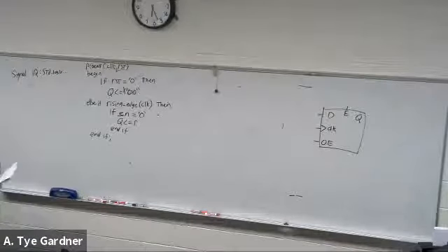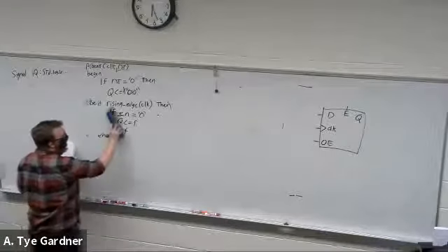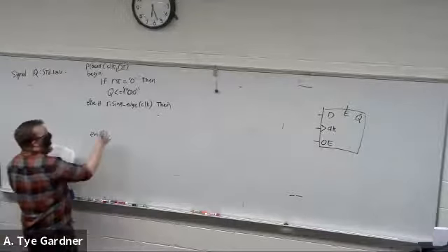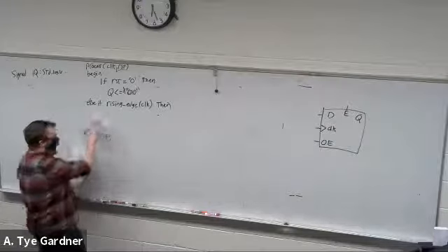And what I'm going to do is say, if I have a rising edge of clock, I'm going to get rid of the enable that way. So I'm going to make an output enable instead of the input enable.